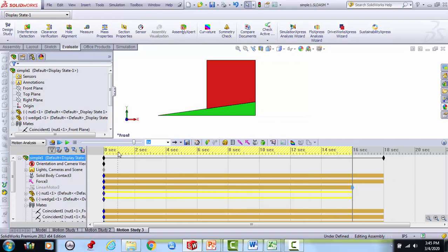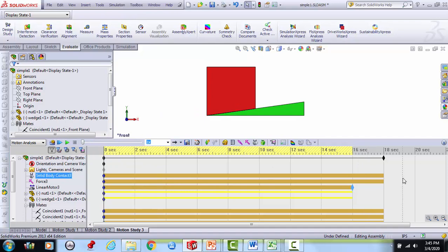I'm going to have some fun with this. What I see when students struggle with motion studies is they'll have diamonds everywhere. What they're doing is they're making changes with the slider somewhere other than the beginning or where you want to put that diamond. So good, important thing to mention. So now let's see what happens. Remember, this is with a friction factor of 0.05.